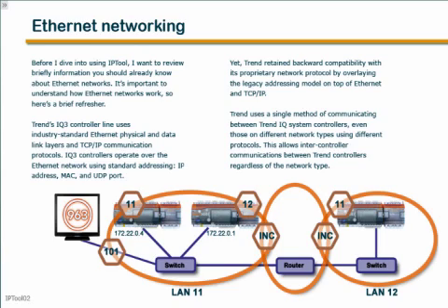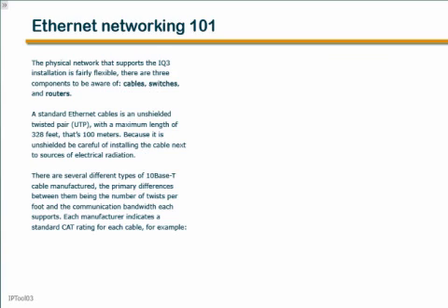and TCP/IP. Trend uses a single method of communicating between Trend IQ system controllers, even those on different network types using different protocols. This allows intercontroller communications between Trend controllers regardless of the network type. The physical network that supports the IQ3 installation is fairly flexible.